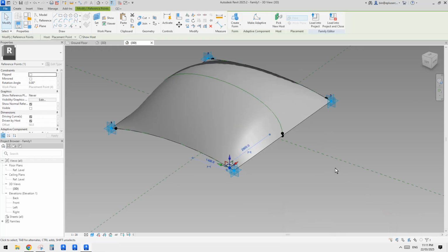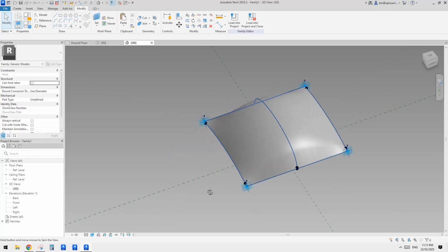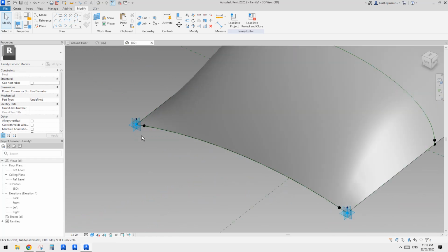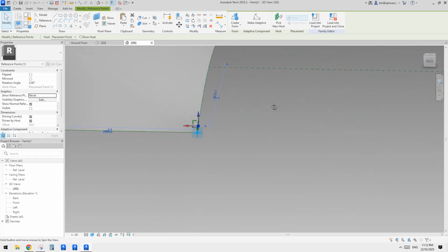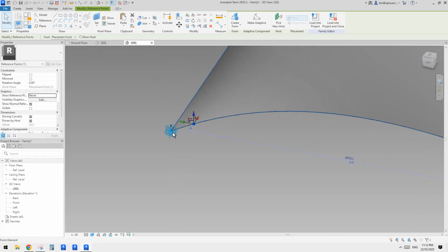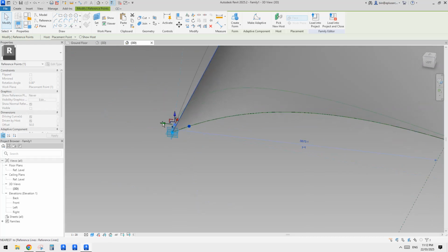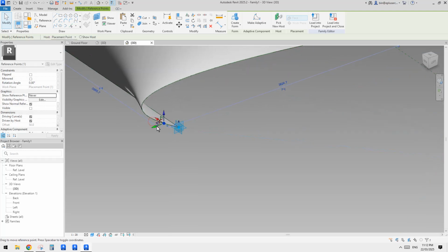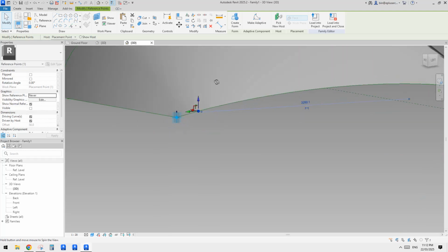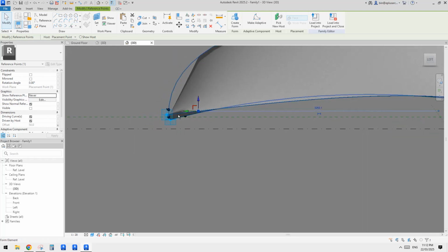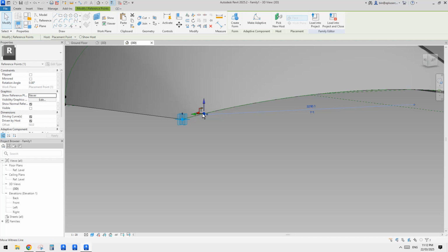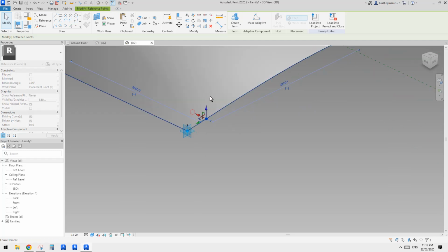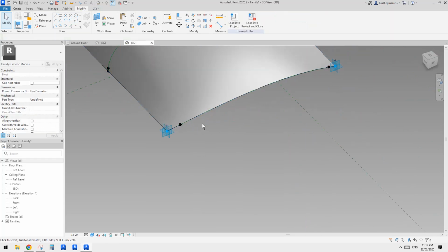Okay, I think the issue with this is that these points are quite like floating in the air, so it's not really constrained onto anything. When we create these points, we offset from the world plane, but they are all floating, right? So we accept the offset, which is the vertical in this family. It's a vertical height difference, but other than that, it's always floating. So I guess it's not ideal.